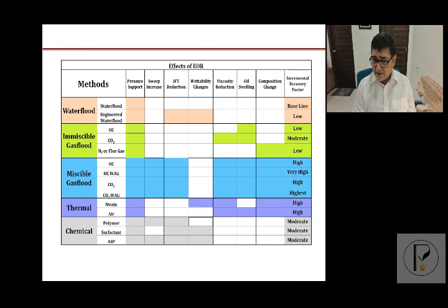These are some particular type of polymers, but most commonly it is used as a precursor to alkali surfactant polymer floods, to modify the existing water flood, cut down on those fingers, make the flood front more or less stable, piston-like, and get some easy oil to be produced.